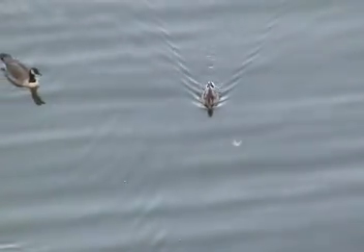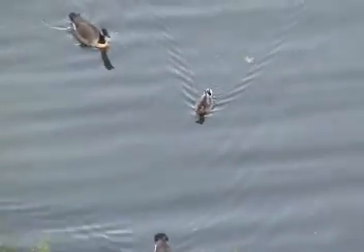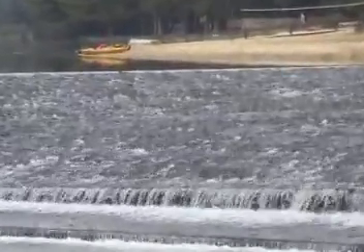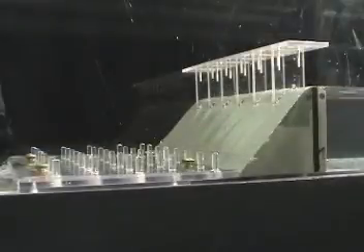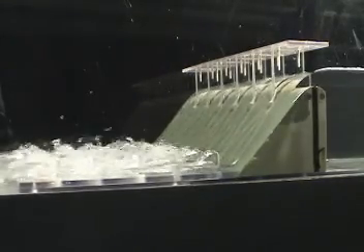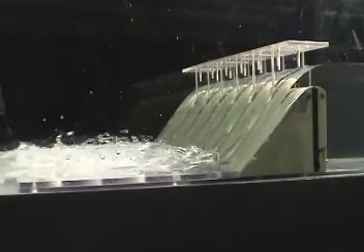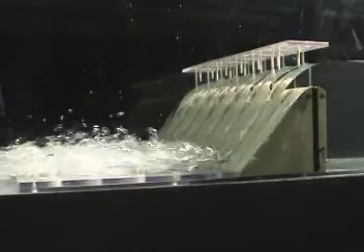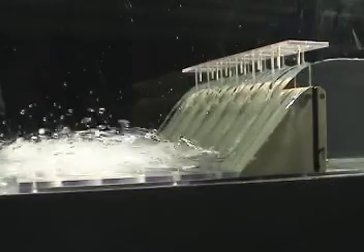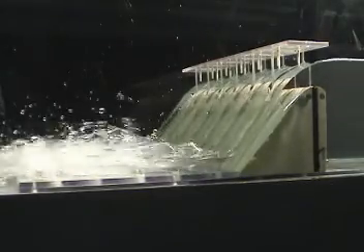There's a strong analogy between these liquid surface waves and shock wave phenomena in supersonic gas flow, where swept-back waves occur when the Mach number is greater than 1. The Froude number is also important in open channel flows, such as the spillway downstream of a dam. In this experiment in a water channel or flume, the fast-moving supercritical flow downstream of the spillway causes erosion of the riverbed. In this flow, the Froude number is the most important dimensionless parameter to match between the model and the full-scale spillway. The Reynolds numbers don't match, but it doesn't matter.